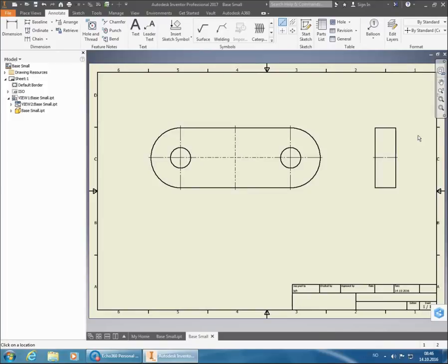And if we're going to be super technical about it, we could have a vertical line on the projected view also to show symmetry, but then we're starting to show absolutely all planes where we can have symmetry. That's not really necessary on this one. So now we've gotten the symmetry lines into place, we can start putting in our dimensions.